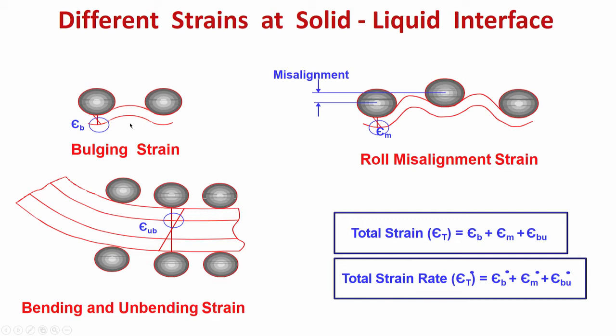So, particularly in the upper segments where the shell thickness is less, and depending on certain grades of steel, when the shell strength is not much, say very low carbon steel or silicon steel or ferritic stainless steel, where the phase is ferritic, strength is not much, and the shell thickness is not much at high segment zones. So, there is a possibility of bulging. If there is bulging, then there is also a strain. It is called bulging strain. We have designated it as epsilon b.